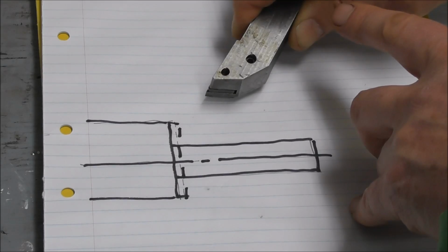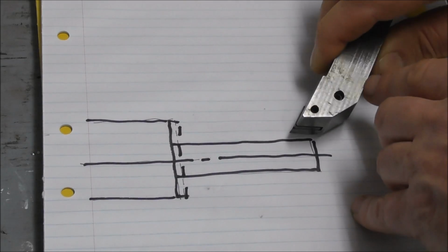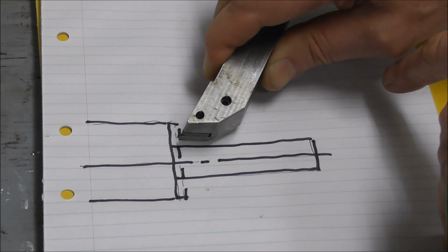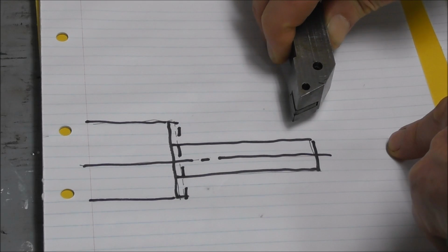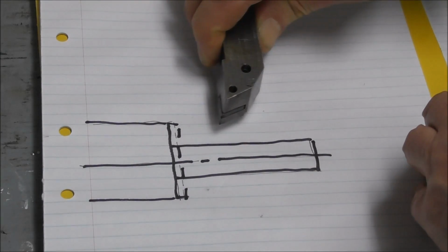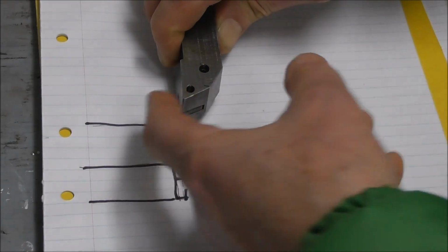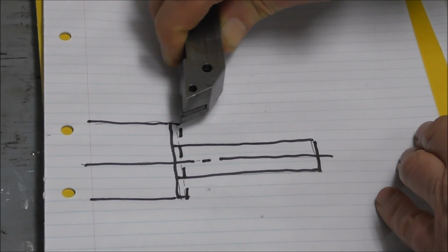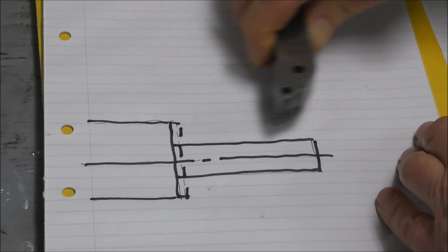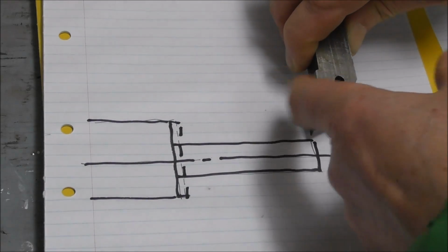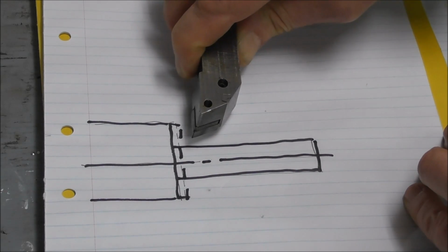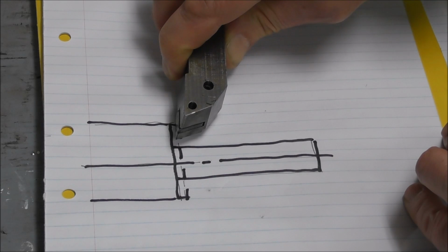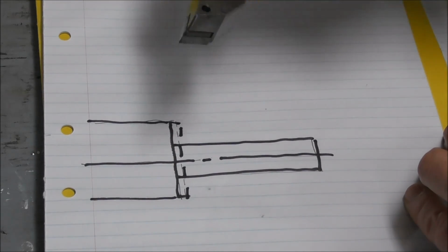Does it back off like that? I'm not sure. But if there was enough side clearance, you might get away with that. But normally you want the turning tool's leading edge without too much clearance. It wants to be almost in line with the part, so that it's cutting with better geometry, and that type of tool clearance situation would cause a massive cut right at the end. And so I would question the strategy if that was their intention.